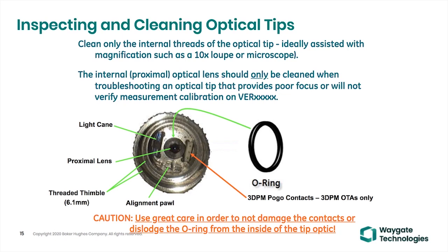So you'll have to screw that tip on. And sometimes what we find is it's easy to have a little bit of oil on your fingers, or it gets on the side of the tip, and then it can work its way inside and get between the inner body of the tip and the outer camera lens, and can create a situation where you have a smudgy image.